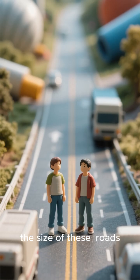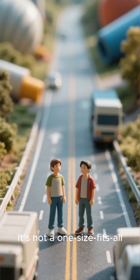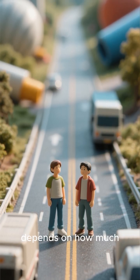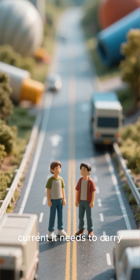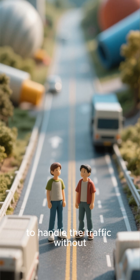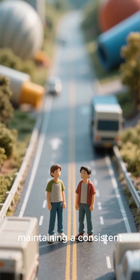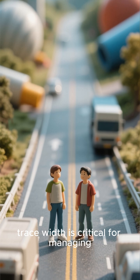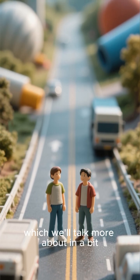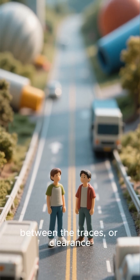Now, let's talk about the size of these roads, the trace width and clearance. It's not a one-size-fits-all situation. The width of your trace depends on how much current it needs to carry. A high-current path needs a wider trace, like a highway, to handle the traffic without overheating. For high-frequency signals, maintaining a consistent trace width is critical for managing something called impedance, which we'll talk more about in a bit. Just as important as the width is the space between the traces or clearance.